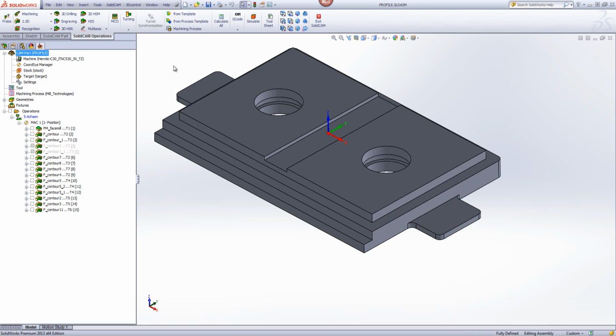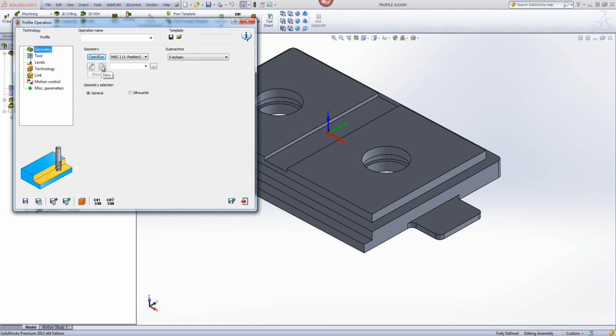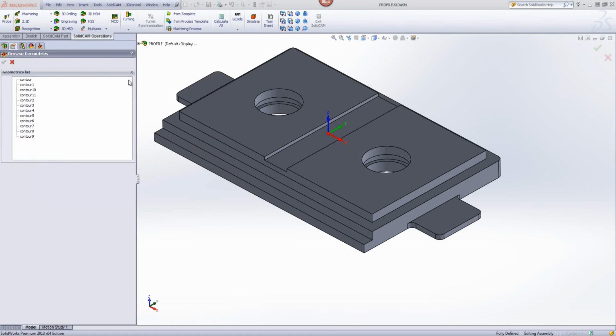Okay, so I'm going to use actually a smaller end mill. And I'll start a new operation of face mill. What I've actually done is I've milled out already up until that area over itself. I'm going to start a new operation of profile. Sorry, profile I said. My geometry, I already have it. I believe it's this one. Sorry, no, this one over here. There we go.